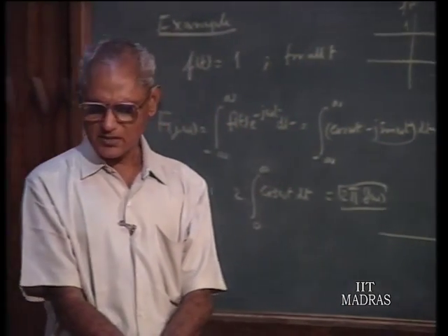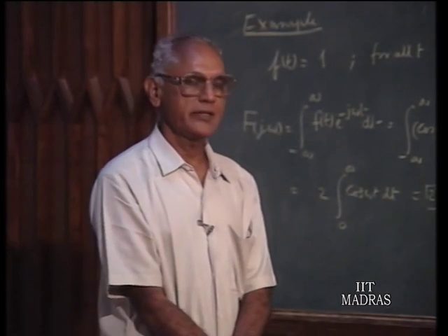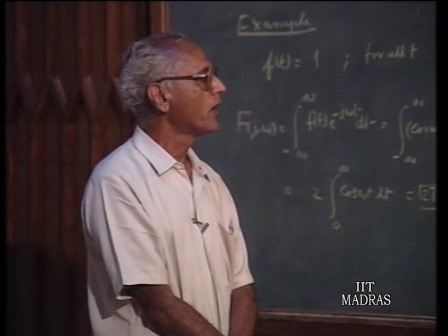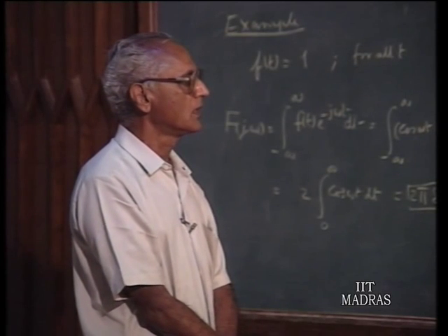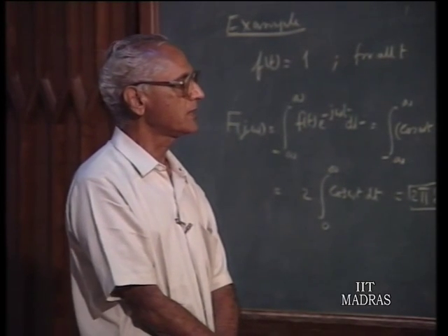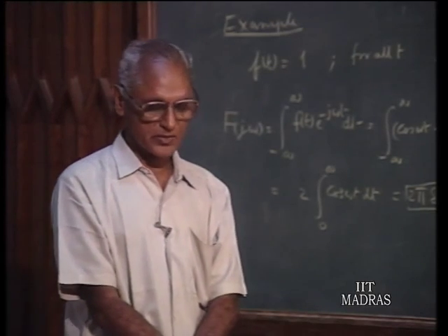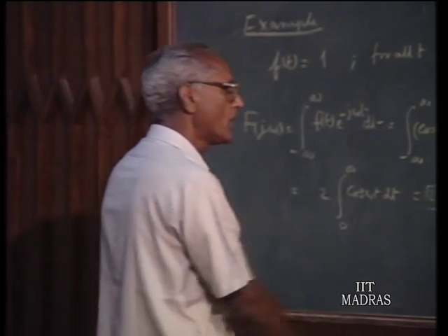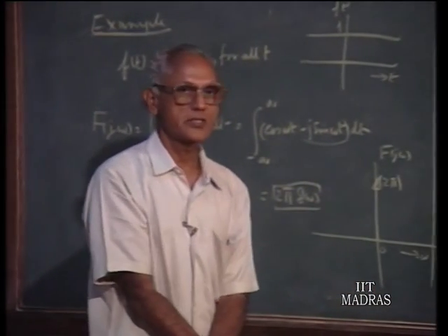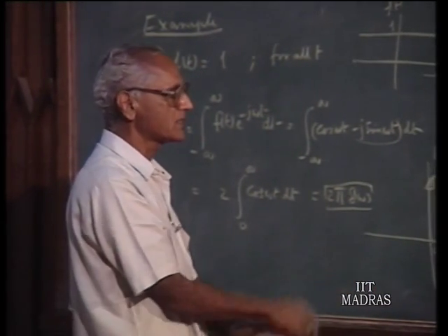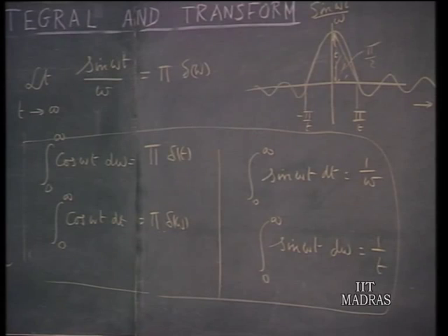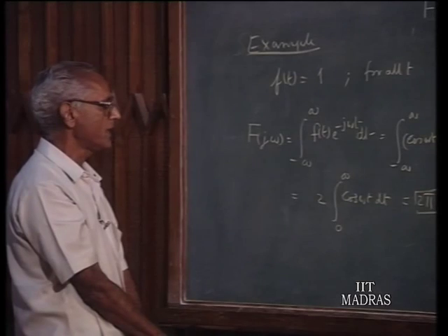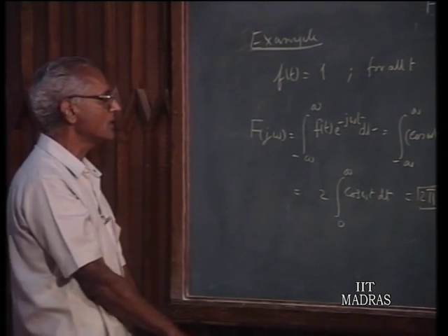Then we discussed the possibilities of extending the Fourier analysis to signals whose energy content is not finite, and in that context we started with some interesting relations involving sin theta by theta functions, and we familiarized ourselves with the sine integral. Then we put down some results which are sanctified by the distribution theory in mathematics, which we cannot prove by classical methods. We assume these results, and making use of these results we tried to find out the Fourier spectrum of a pure DC quantity